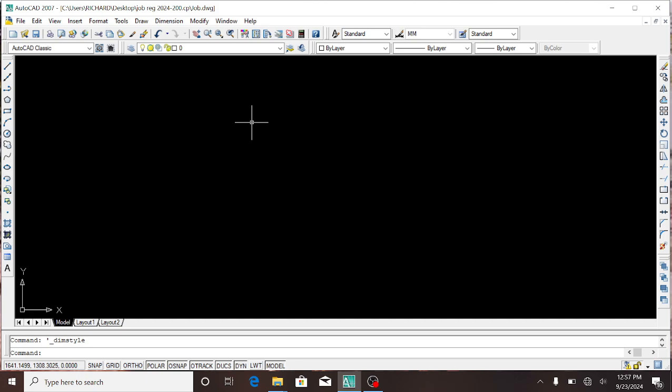And then another setting we can do is we set the layers. Layers, normally you set according to the work you are doing. If you are drawing a floor plan, you have the text that describes the rooms, the dimension that shows the room space, the wall that surrounds the room space and divides the house into rooms, the window that brings light and air circulation, and the doors for the entrance. So all those you create as different layers.